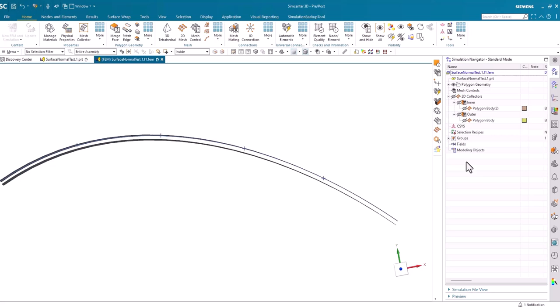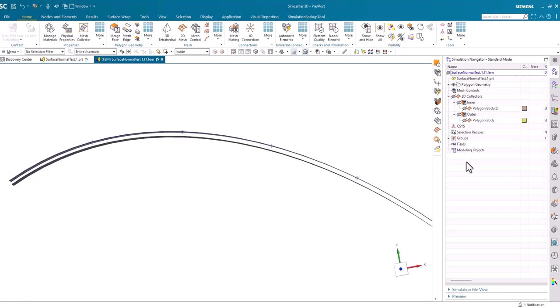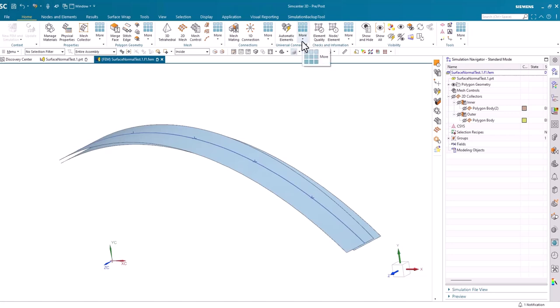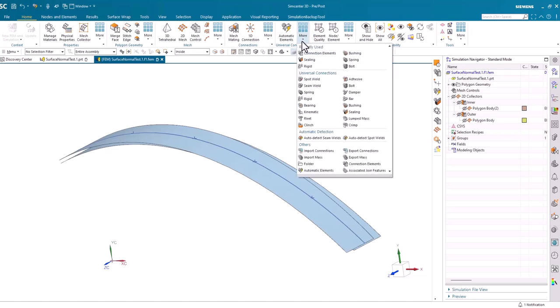as spring elements, C-bush and RBE3 in the Nastran language, and then the spring elements will be spanned from one point on the top surface to a projected point on the bottom surface, and their orientations will be based upon a coordinate system that is created when we export the model for solution. So let's get started with respect to defining our ceiling connection.